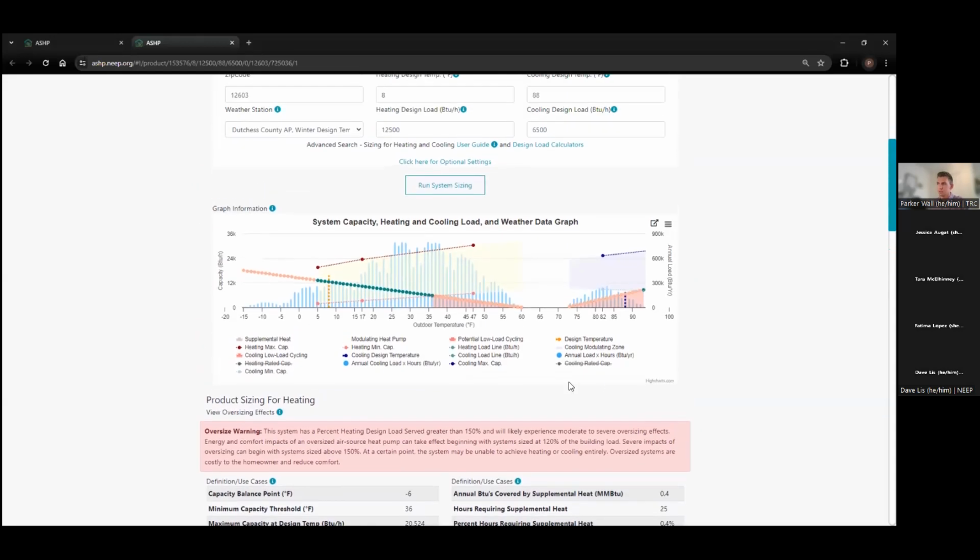Now, I know that some of this is going to be latent load removal, but because the sensible heat is what's shown here, really, in order to dehumidify the space, you're going to have to run on really low dehumidification speeds, or the set point of the temperature is going to have to be low, and that space is going to be, once it gets dry, it's going to have to be cool, because this heat pump is going to have to turn off and on, and add a lot of cooling to the space, and it's not going to be able to run for long periods of time, which is how it best wicks moisture from the air.